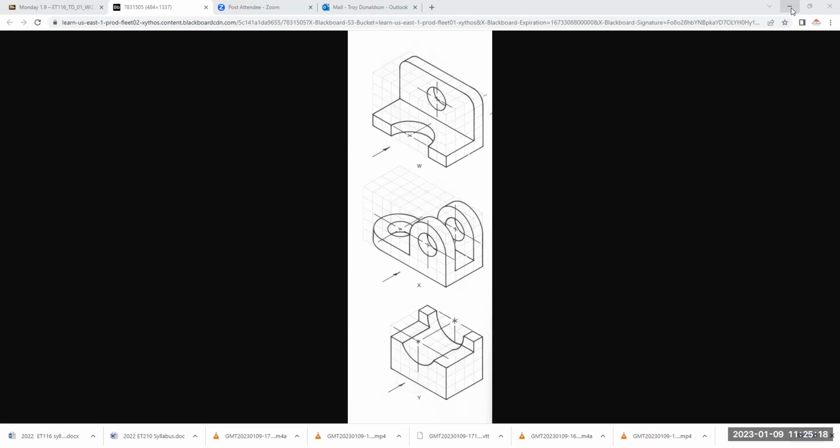TR enter is faster for me than going up and trying to find it, most of the time, because I can't find the thing I want and I get frustrated. But trim's been improved in that you can just draw a line through what you want trimmed. So that dotted line, whatever it goes through, trims. If you haven't run AutoCAD recently, that's a major improvement. You do not have to select objects.